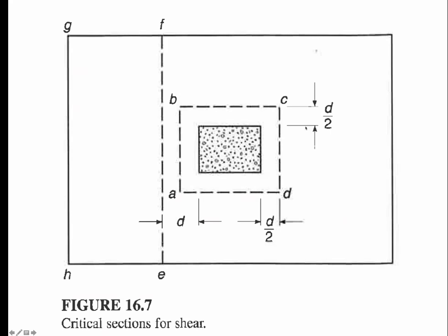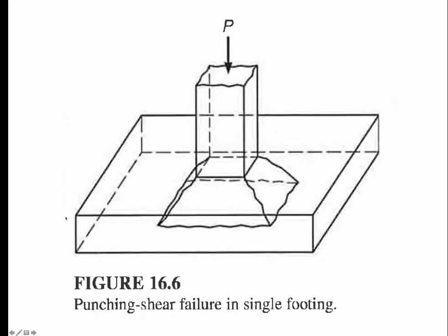And D is going to indicate the height of the footing, by the way. Let me back up and show that. This will be D, the depth of the footing, and that will be from the top of the pad down to the reinforcement steel. So there's still going to be a little bit of concrete down here, which is considered cover. That cover is not considered in this design. That would be gravy, a little bit of extra capacity, so that's all good. But it is not included in the calculations solving for shear.